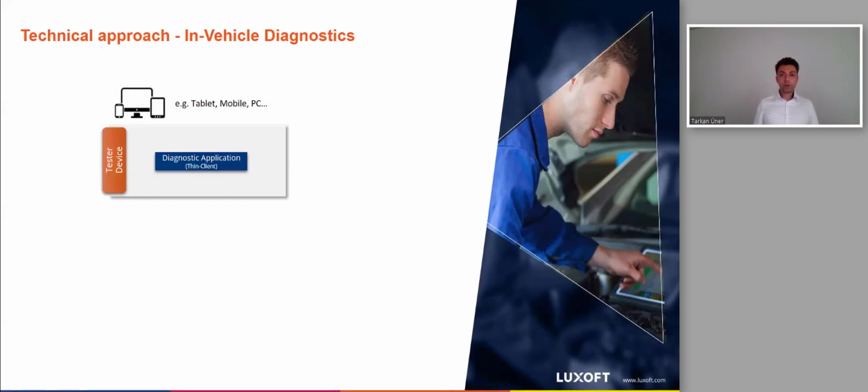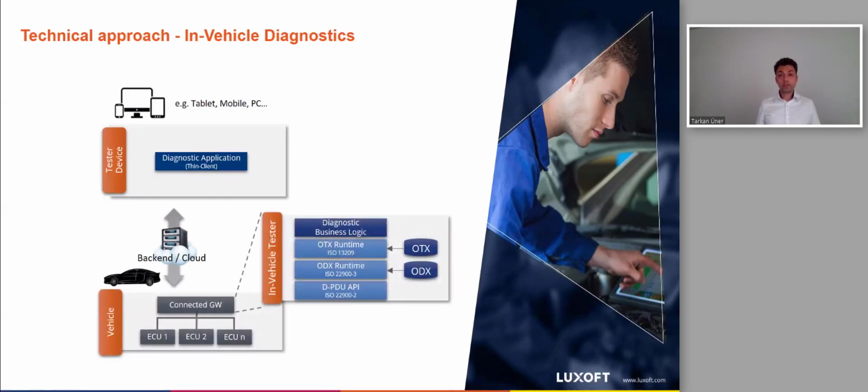This conversion from an off-board tester to a fully functional onboard tester leads to vehicles diagnosing themselves. However, some new hardware systems will ensure that the self-diagnosis also works. Here, for example, high-performance computing platforms could get into the car, and it will take control. This means that all runtime functions like OTX, ODX, etc. are now running in the vehicle. ECUs will, of course, not completely disappear from the car.